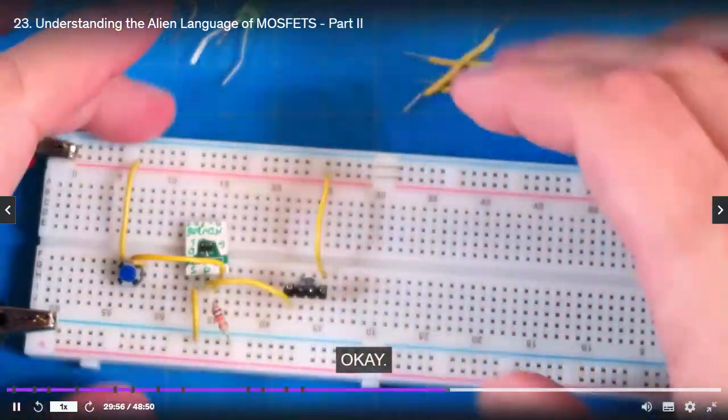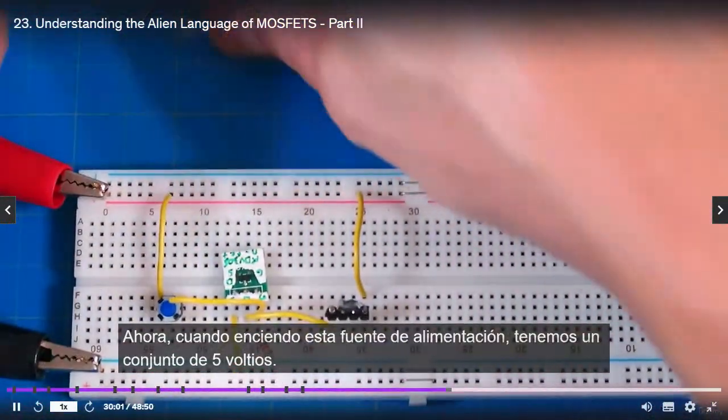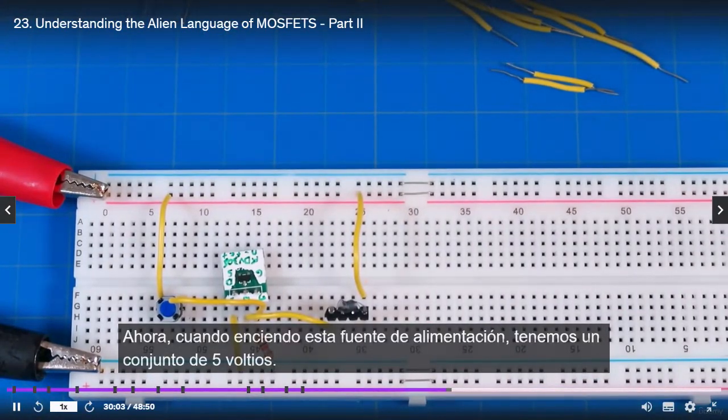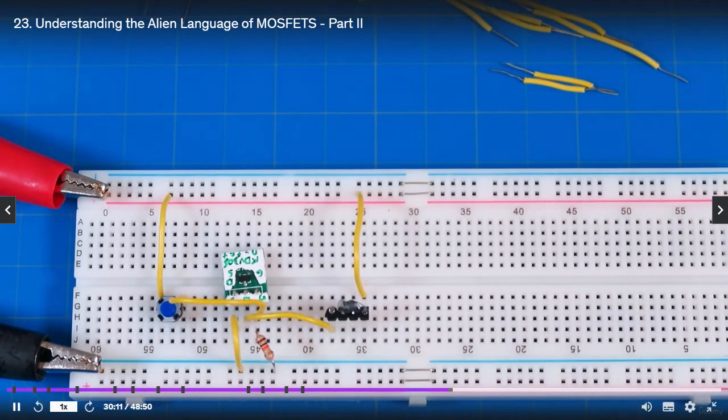Now, when I turn the power supply on, and we've got it set for 5 volts, we should see nothing. Nothing should be on because we've got this thing pulled low. So VGS is 0 right now. I'm going to turn it on. Everything's good, 0 volts like we expect.